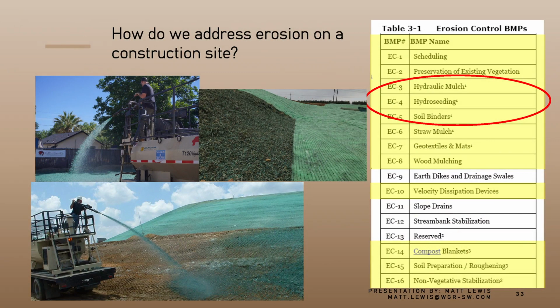All right, moving on. As I said, soil binders, mulch and tackifiers are temporary BMPs lasting 3 to 12 months generally, depending on how significant your rainy season is. I've seen them last a little bit longer. I've seen them not last long at all. Be sure that they are applied according to the manufacturer's specifications and instructions, and be sure to provide ample cure time to prevent chemicals from being transported by stormwater runoff.